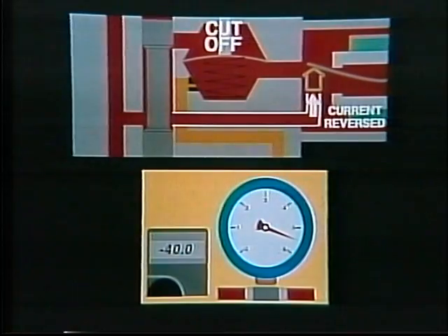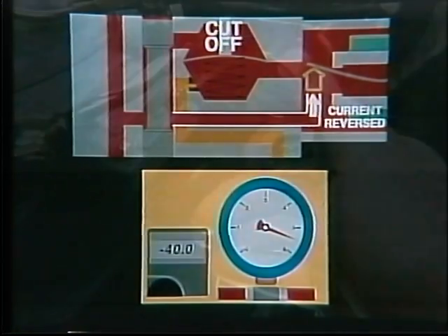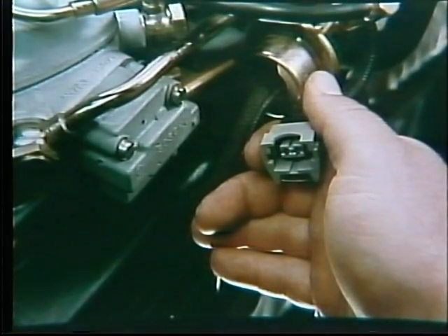To cut off fuel injection, such as during coasting, current is reversed to move the plate completely away from the inlet. With no limit to the inflow of actuator fuel, system pressure is in both chambers, so the spring pushes the diaphragm up, closing the outlet and cutting off injected fuel. When you pull the connector, the warm engine runs, but runs leaner than with a typical 10 milliamp actuator current. That represents a limp home condition.